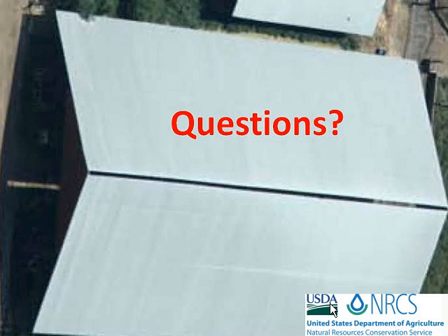It depends on whether you have the smooth pipe inside of the corrugations or not. A lot of those pipes are, and I would expect you'd use the smooth-inside version. Manning's n for those pipes is a look-upable thing. Right. For a smooth pipe, it'd be 0.012. I think there was a slide in here that said it'd be typical for a smooth surface.